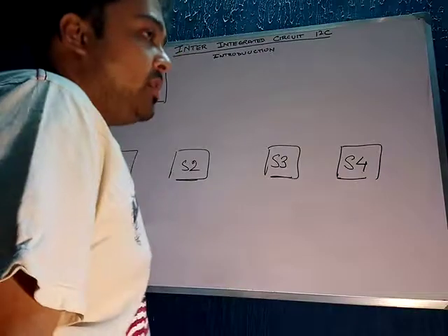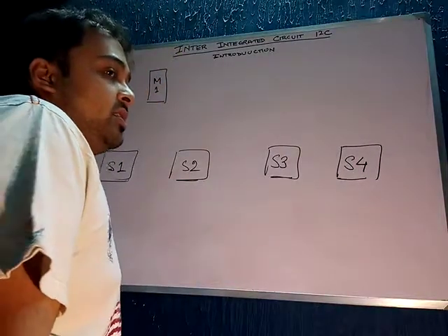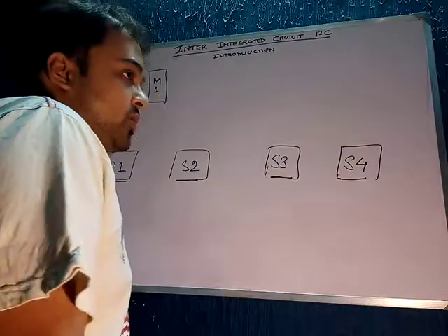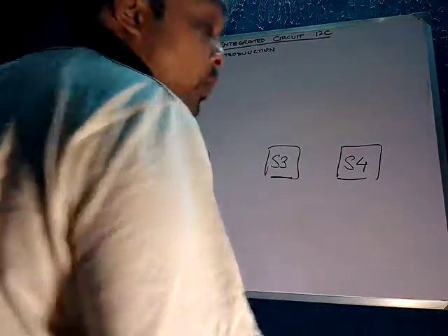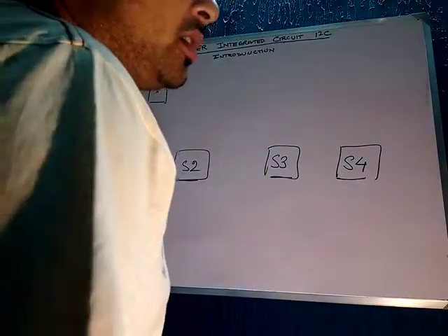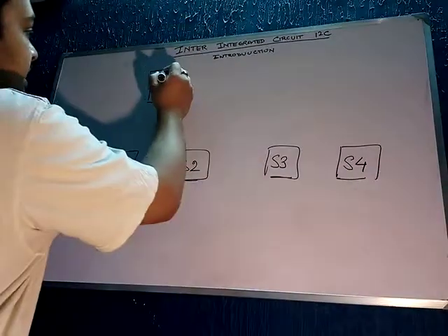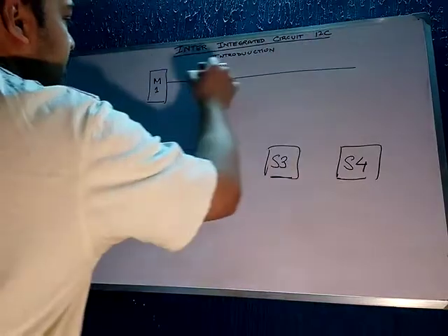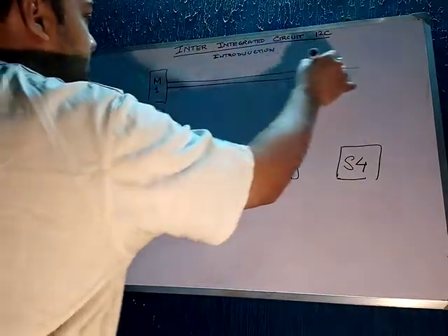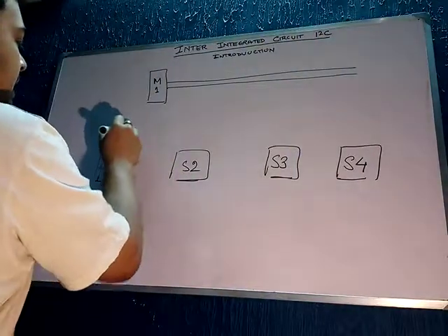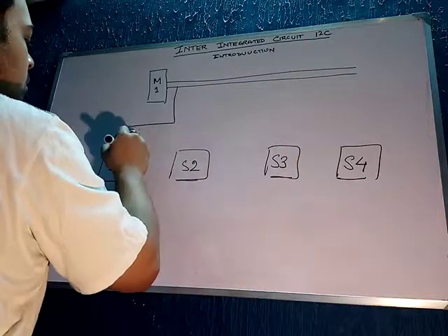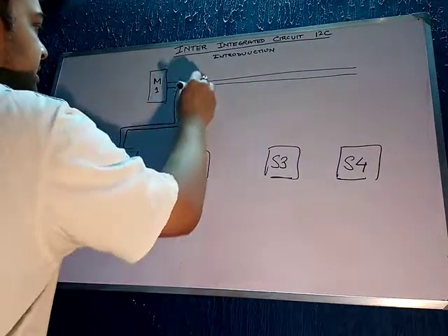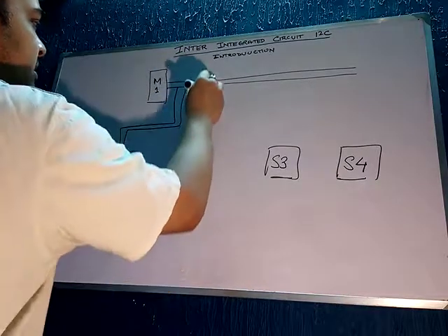One of the most brilliant procedures that was really discovered by Philips was to use a two-wire technique. That is why it is called a two-wire interface. That is, just have two wires, and all the slaves are connected in parallel to the master.